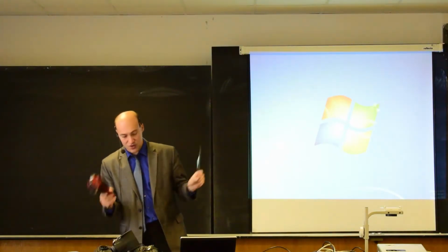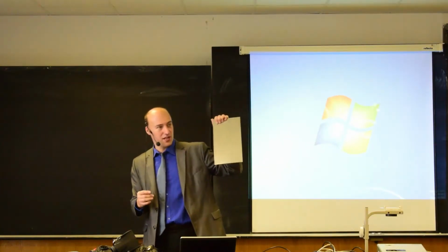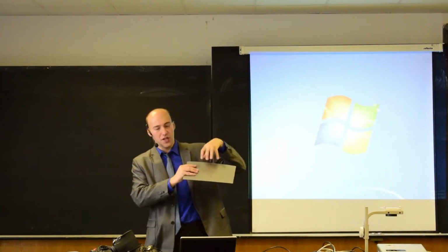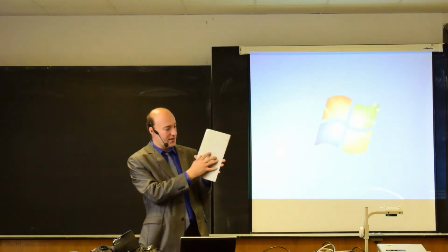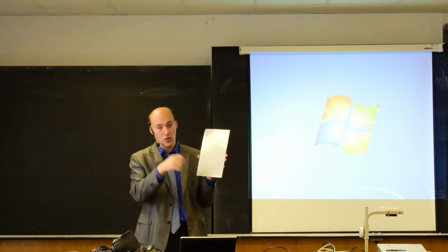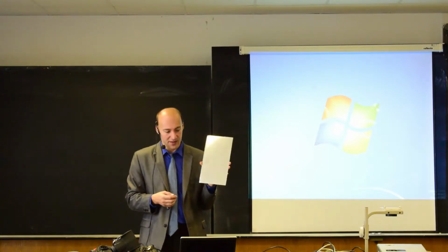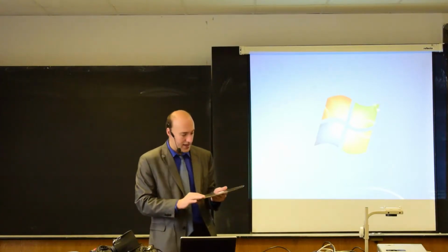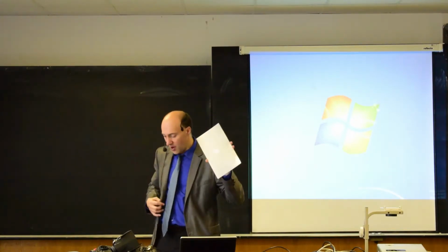So try this out. Here, for metallic materials, it's really difficult to measure the temperature of the object itself, because you are always getting the reflection. So this material has a low emissivity. It's stainless steel, but also the same behavior is for the aluminium, copper, and basically all metals. So if you want to measure the temperature of such shiny objects, then it's quite hard to do that.